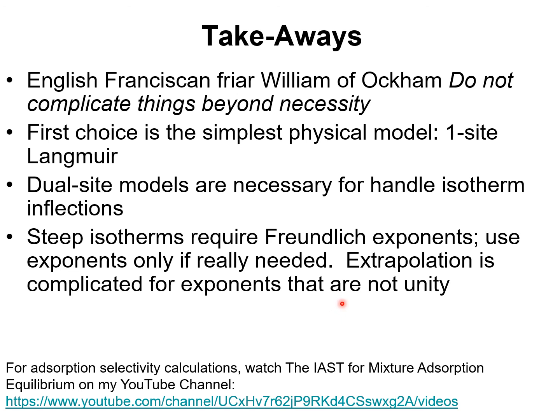The isotherm data at different temperatures can be fitted simultaneously using temperature dependent parameters, and the advantage of this approach is that the T-dependent parameter model can be differentiated analytically to determine the isosteric heat of adsorption. Once the isotherms are properly fitted with the appropriate physical model, then the adsorption selectivity calculations can be carried out, and for this purpose you may watch my YouTube presentation on the IAST.